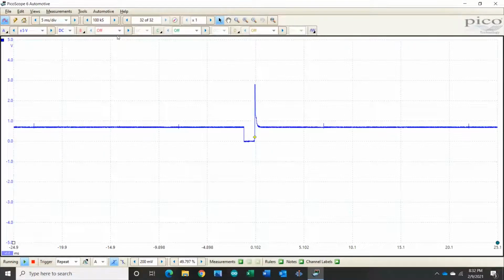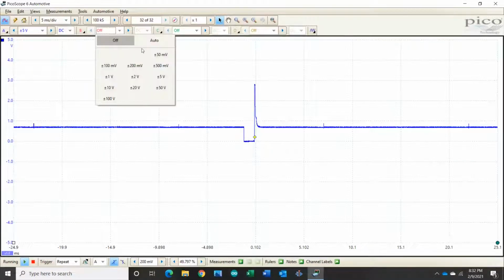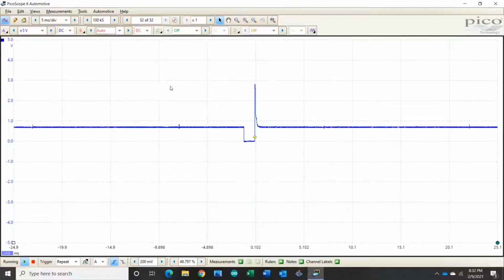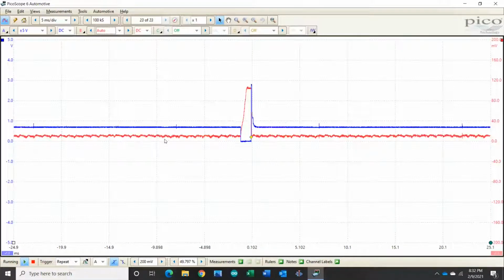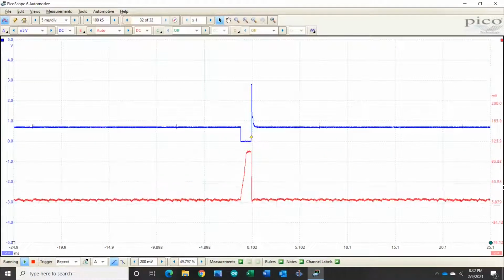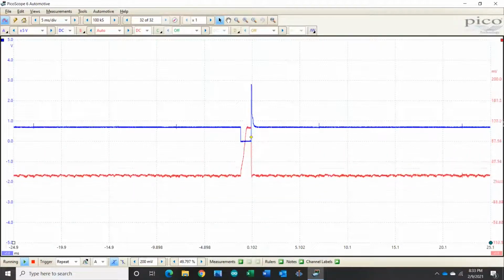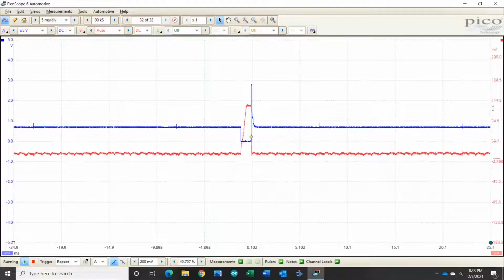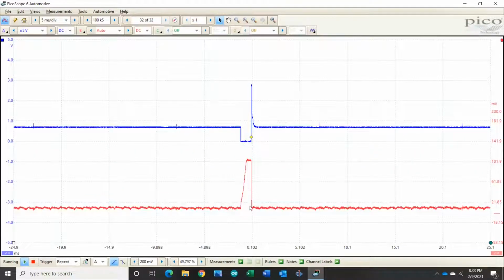And then here I'll give you an example of turning another channel on. So this is again in demo mode. So now we can turn on another channel, and you can see there the red waveform. We have another channel turned on, so that's what it looks like if you have more than one voltage reading. And as you can see, we can drag these around to move them out of the way. So here's an injector voltage and current, it looks like, is what they're trying to show here in the demo mode. And the red voltage numbers here apply to the red voltage waveform.